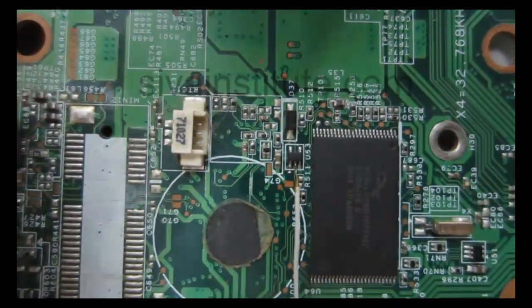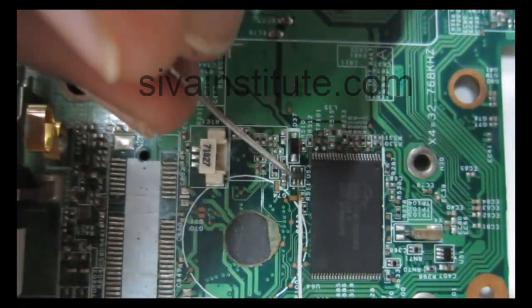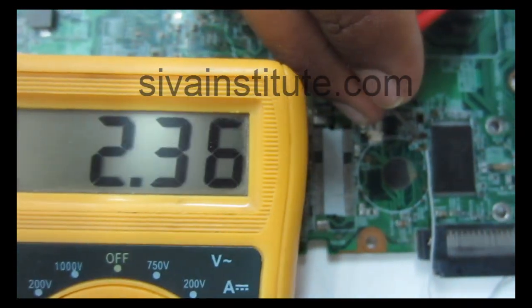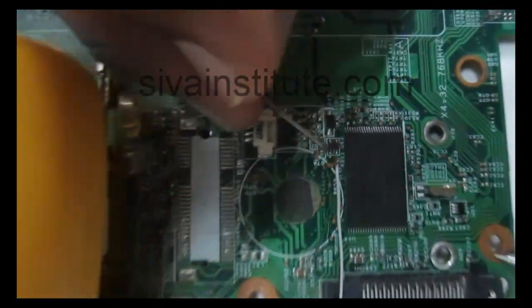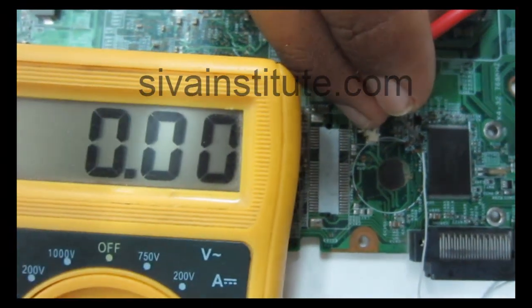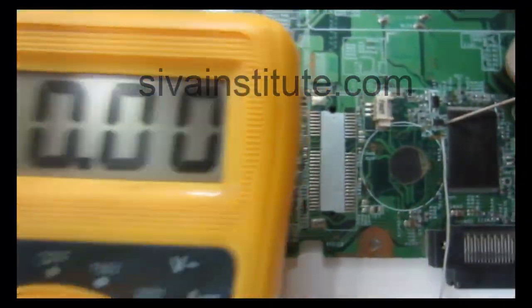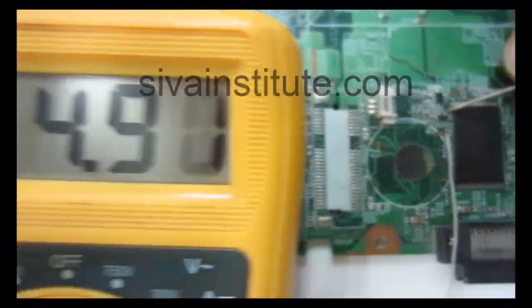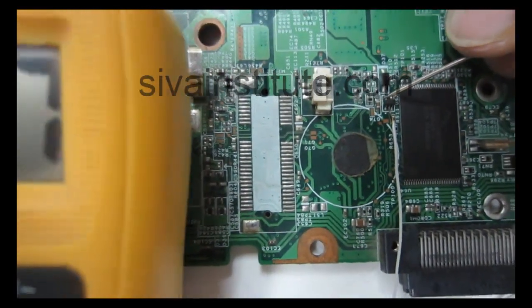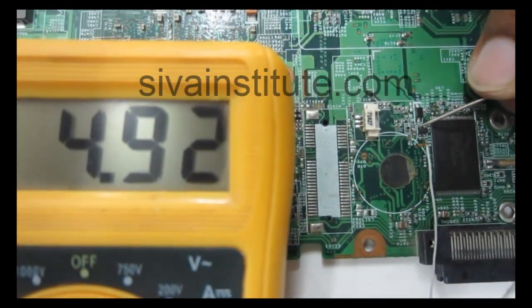This is the U63 5 pin IC. We will check without the SPI command. Pin number 1, 2.3, nearly 3 volts. Pin number 2, no voltage. Pin number 3, no voltage. Pin number 4, 4.9 volts. Pin number 5, 4.9 volts. We will give the SPI command.